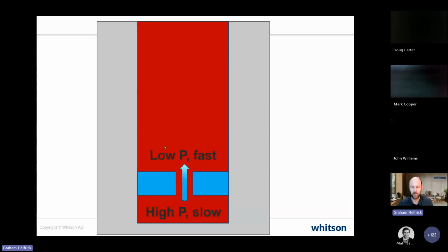Why does this matter? One of the reasons people might use a downhole choke is they want to control the rate of the well and the drawdown, but they may want to avoid liquid loading above the choke in the tubing. We may find that below the choke, the well might be liquid loaded because the fluid is so compressed and moving more slowly. But on the outlet of the choke, because the fluid is more expanded and moving faster, we may be above that Turner velocity or critical lift rate, so we may be unloaded.